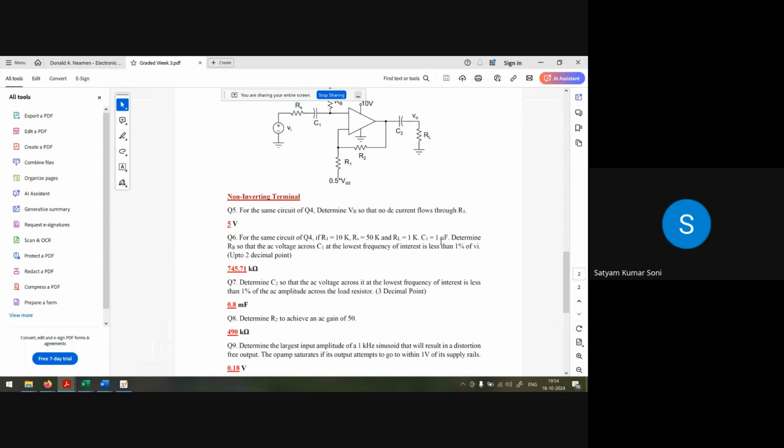Up to 9 volts, not exactly 9 to 11, up to 9 volts. Because 10 volts is the maximum supply, the maximum output value is the lesser of the two, 1 volt within the higher supply. The supply is 10 volts, so the maximum output possible is 9 volts.